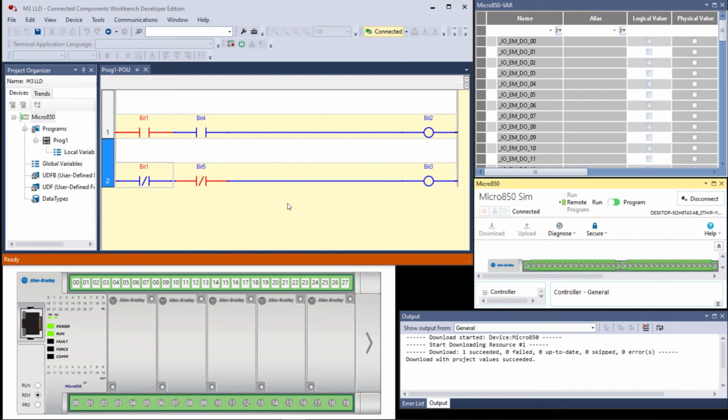And that's pretty much what we did in this lab project. We went from one rung to two rungs. We went from multiple conditions or permissives, the true false stuff, to see how it affected the state of the bits addressed by the OTEs, or the direct coils, if you want to call them that. Because remember, these have a true and a false execution. This instruction does something to bit 2 if the rung's true, and something different if it's false.